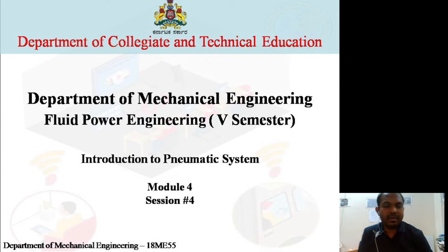So here I'll be concentrating more on this FRL unit. As I was just talking about this FRL unit, FRL stands for the filter, regulator and the lubrication system. Now mark, though these are three different equipments, they are termed as one simple single component. It is only because the objective of using this FRL remains the same, and they make a maximum difference to the system of the pneumatic